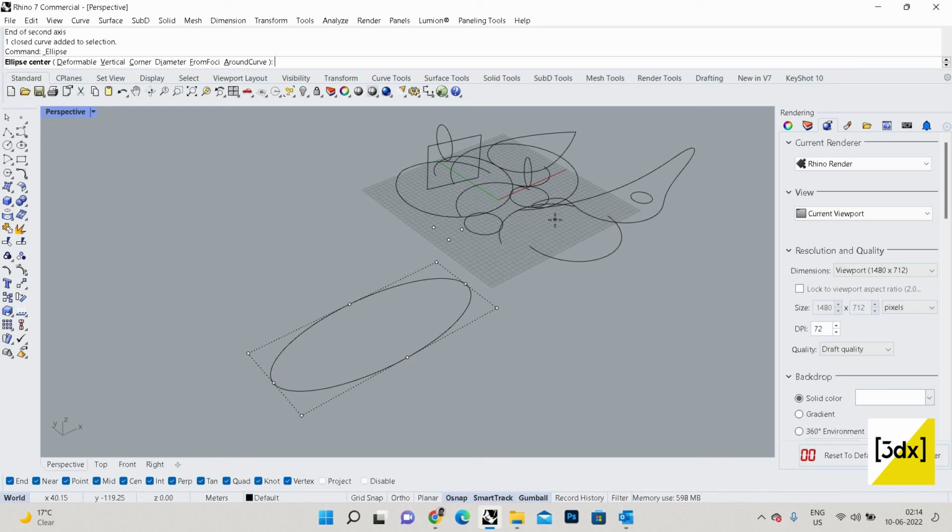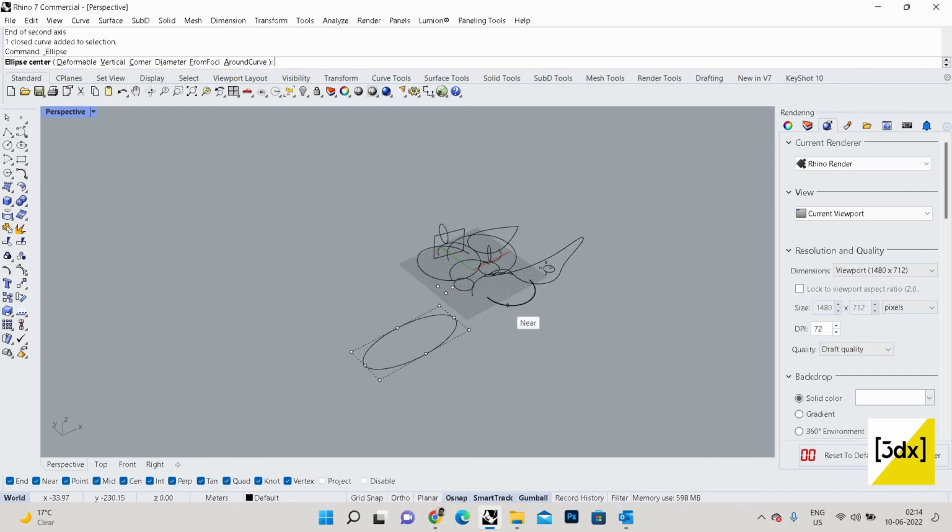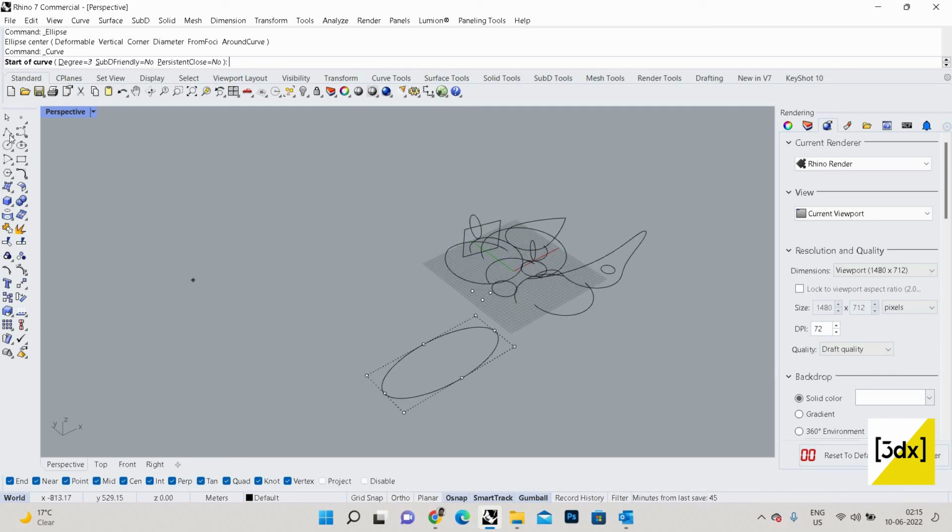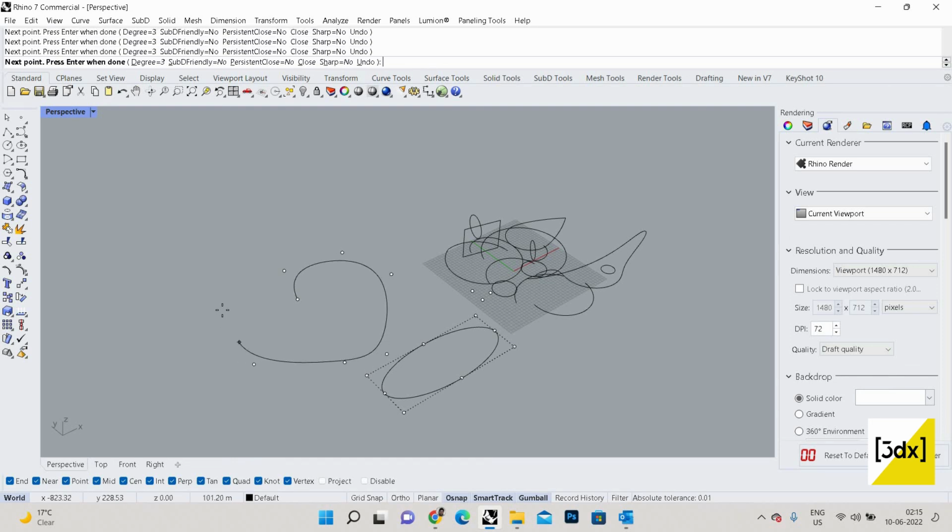So after this, these are the major 2D parts. These are the curves. You can see polylines, circle, arc. So this is a curve. So in curve, let's see what these options are. These are control point curves. I said you know what a control point is and how the deformable option works. So with this, you will check the control point. I'm just taking the first thing, that is control point curve. You can see I am drawing a curve by clicking the control points.